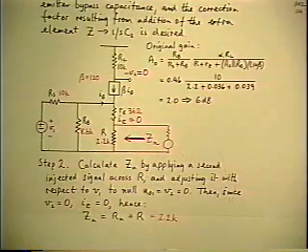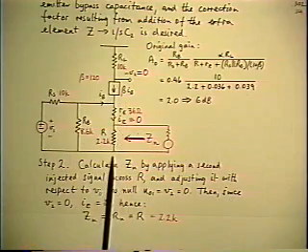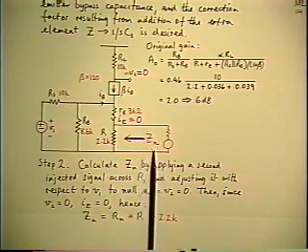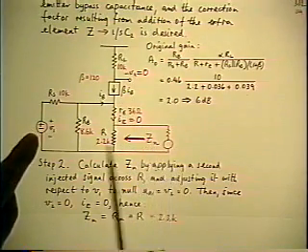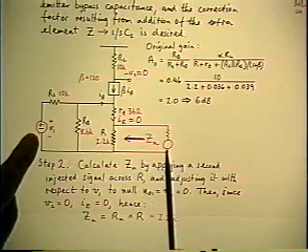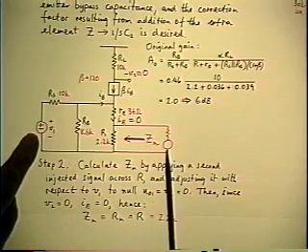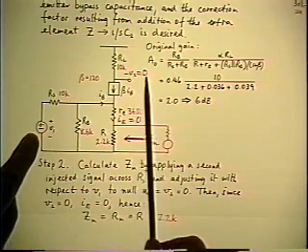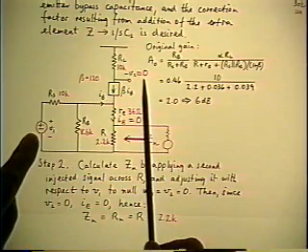In fact, let me repeat the derivation of the Zn yet a third time. Back to the first method again. Remember, the way you calculate Zn is you have both sources present, both the original input and the second source for test purposes. You adjust the two of them in magnitude and phase until the first output nulls.